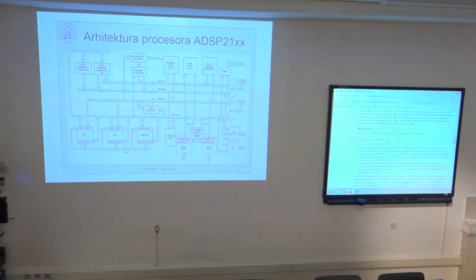So the idea is, this kind of very long instruction word architecture makes sense only if these executional units have additional data registers that can be used as arguments at the input, and which can be used also to directly store the result of the operation to one of these data registers.